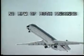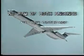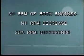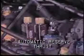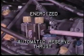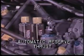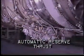During takeoff, an aircraft onboard computer senses and compares the N1 RPM of both engines. If either engine experiences an N1 speed decrease, creating a 30% RPM difference, the computer energizes the automatic reserve thrust solenoid on both engines' fuel controls. The fuel controls schedule additional fuel, and the increased fuel flow causes a thrust increase on the engines.